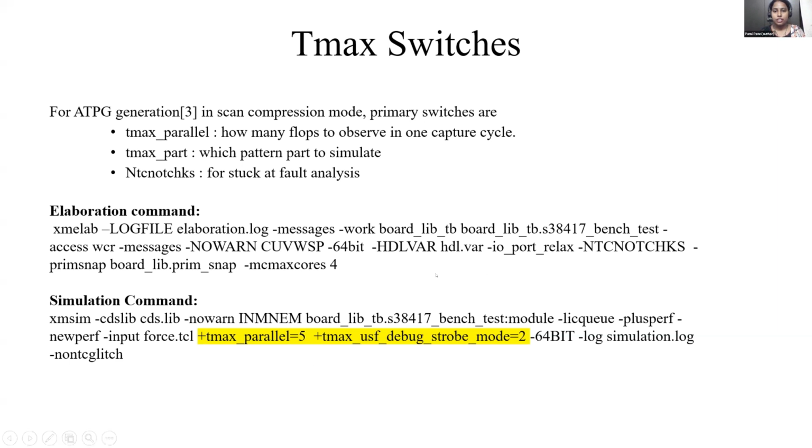So here in HDL, we are setting the environment for simulation. No timing check is just for letting the simulator know that it's a stuck-at fault model we are checking. No timing. We are not checking the timing issues or delay testing. It's not a delay testing.